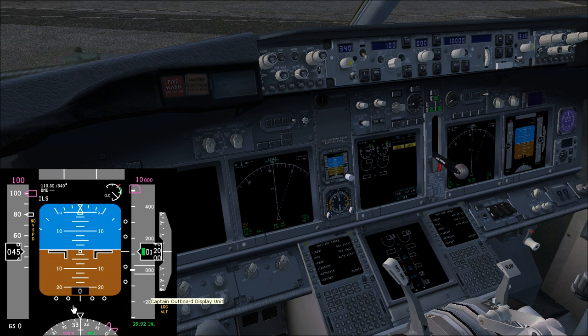the full deviation scale for the ILS. Actually, the ILS is selected here, and as you can see, we have a frequency, a direction, and a DME distance that is not displayed, and elevation indication. In this position here on the top left corner, you will see all the indications about what you are now seeing on the scales. Actually, if you are working with LNAV and VNAV scales, you will see that those scales are actually RNP or navigation performance scales with actual RNP or ANP, and actually you will see here LNAV VNAV.